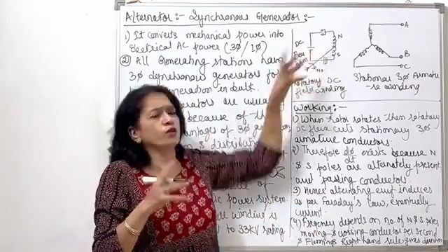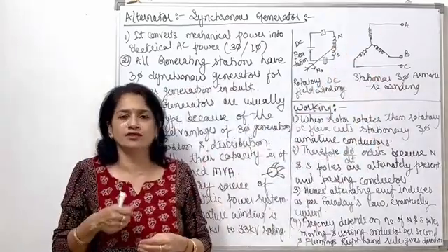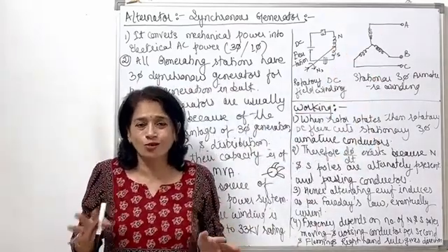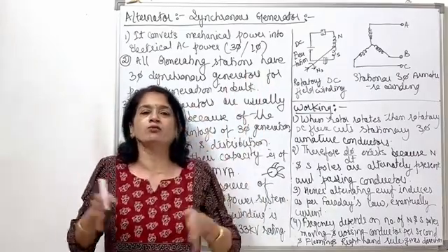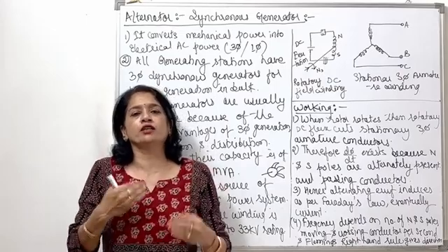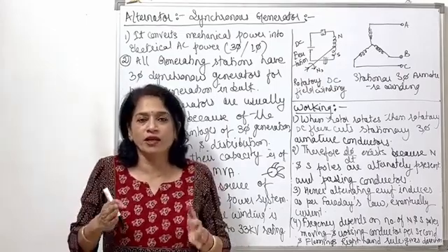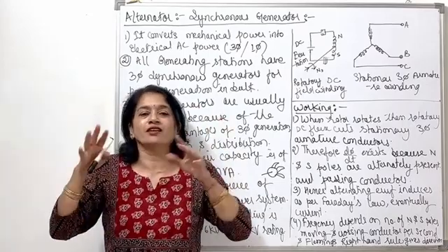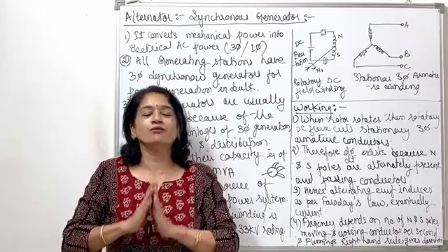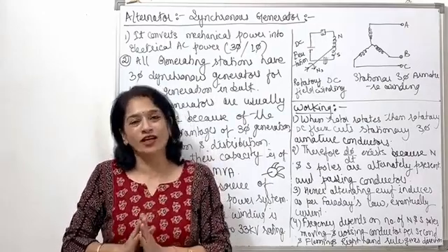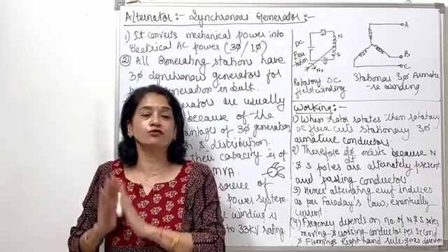Right now I am giving you only a 2-pole example, and 3 phases are there through 36 conductors. Here the 36 conductors are not mattering, beta. I am just telling you in what pattern the number of conductors are associated with a single phase. But how the conductors are placed in the slots of the stator is a different and long discussion. I'll be taking it up in 4 to 5 lectures about the armature winding of the synchronous generator. That is a different topic.